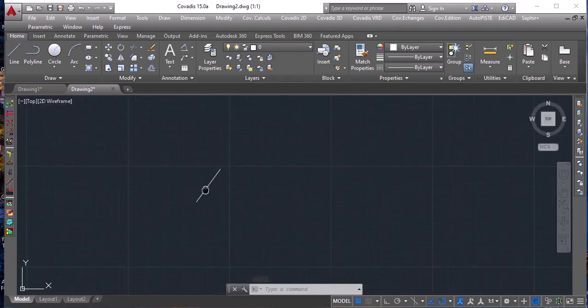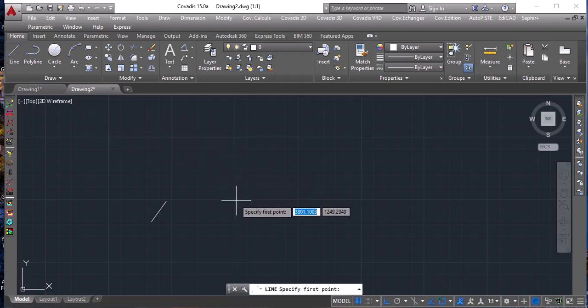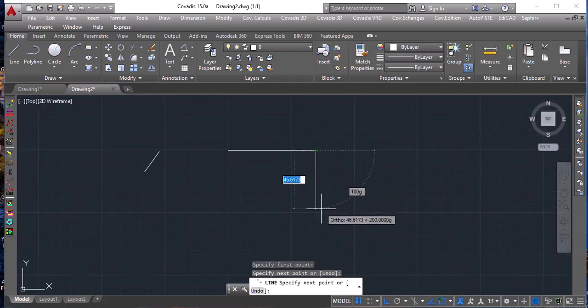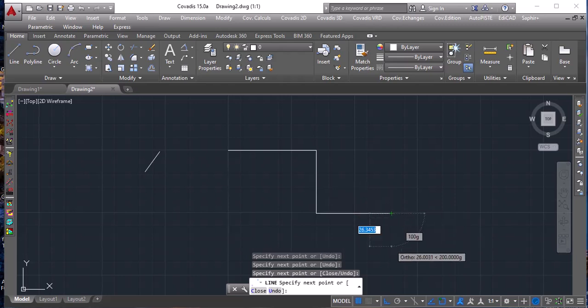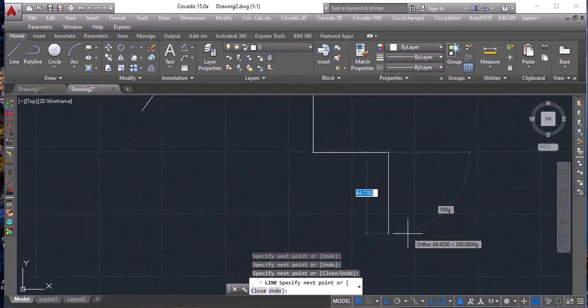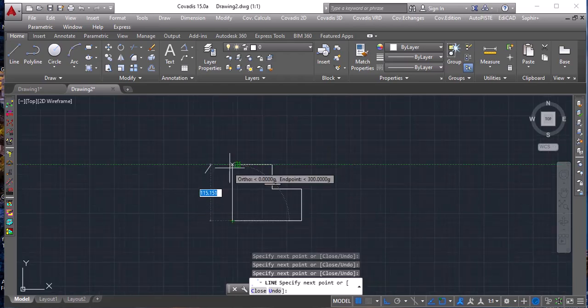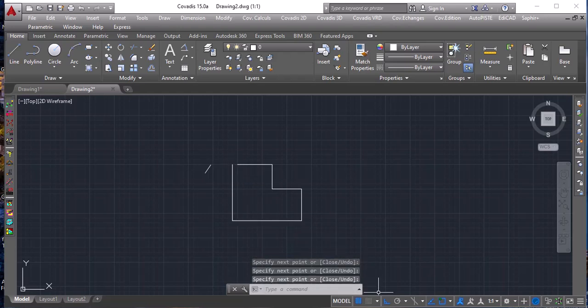Okay, so we've seen the unit, we've seen how to draw a line. You can also draw this line by imposing it to only be perpendicular. I'll come here to this auto mode, then I take my line, to impose my line to only perpendiculars. See, multiples of 90. Anything which is not a multiple of 90 cannot go. Once it's a multiple of 90, then you can draw. It is because of this perpendicular.